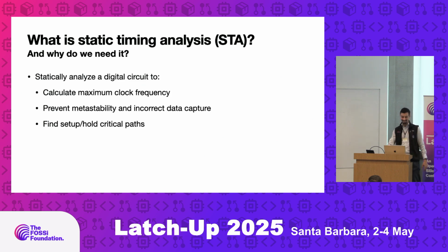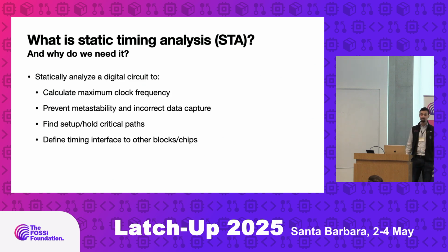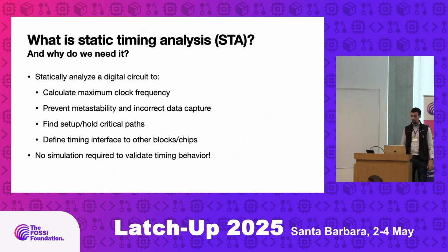And finally, define timing interfaces to other blocks, so people can use your blocks and understand when the signals should be expected to arrive. And one of the great parts about static timing analysis, the reason it's static, is that you don't need any simulation vectors in order to validate the timing behavior.